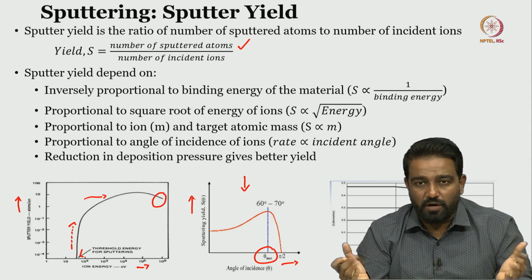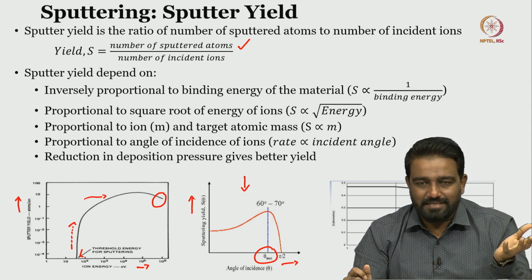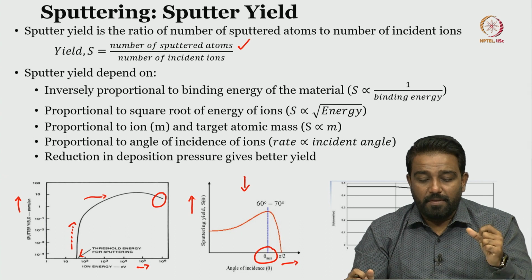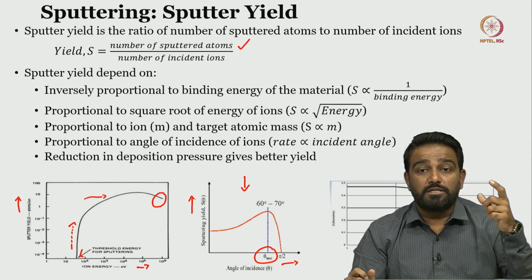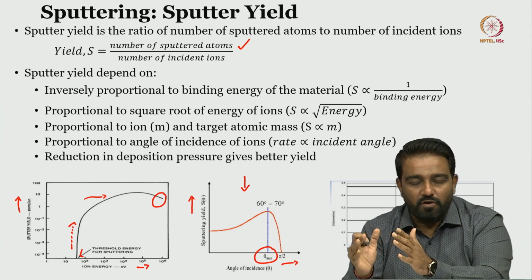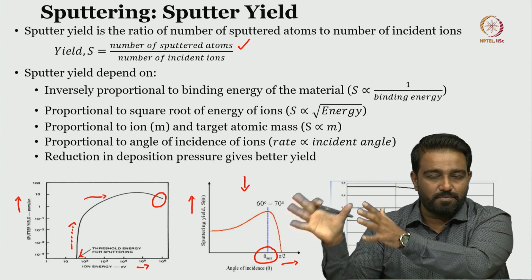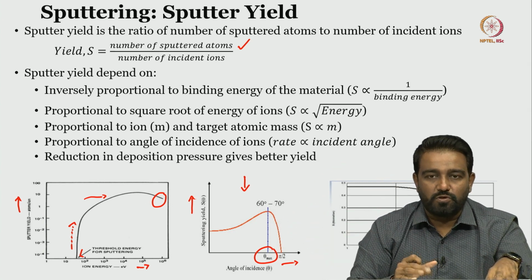then there is a Penning gauge that goes to minus 4 and about minus 7 torr, and then how the deposition occurs within the chamber. So, this we have recorded for thermal, for e-beam, and for sputtering. You can see those recorded videos from the experimental laboratories as a part of this course.